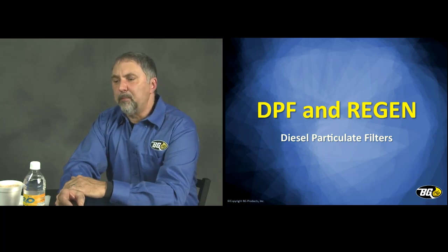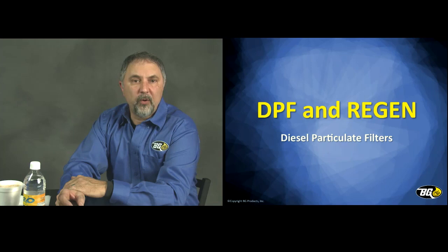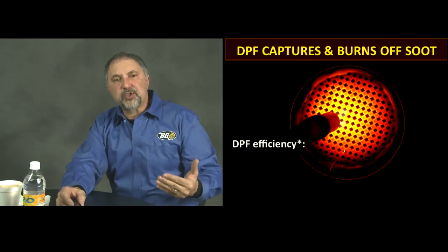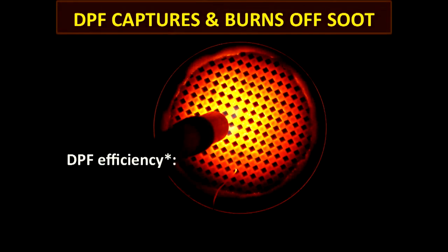It's not like a toilet bowl that once it gets plugged, it has an overflow that allows it to drain back in the tank. There is no such thing. This engine will shut down. The DPF is designed to capture soot and burn that soot off. Now we have to get into the term soot, and we'll define that.